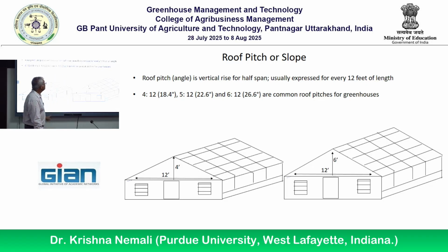Does it make sense how the roof pitch increases light transmission? You want a roof with an increased angle, not a wider one, but a steeper one to get more light into the greenhouse. The common recommendation is 6:12, by the way. Remember that, 6:12. A low profile Venlo style has 6:12 maybe, but the other one, gable style with high profile, may not have that 6:12. Remember that, right? 6 for this and 12 for this.